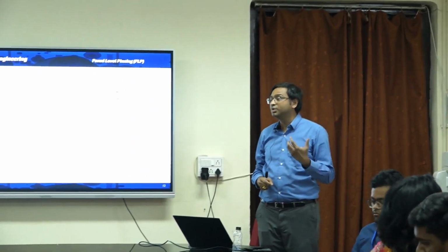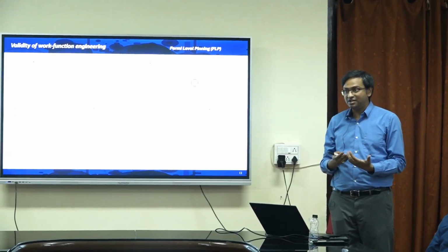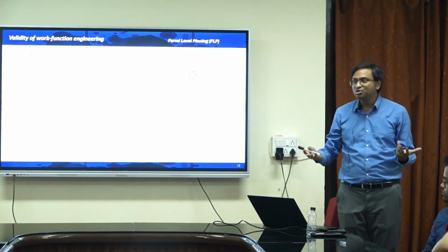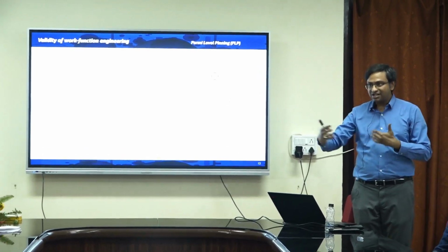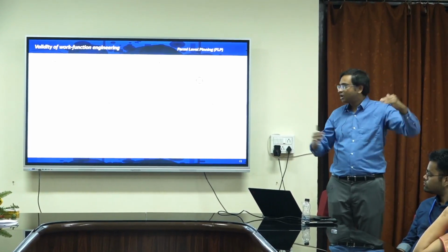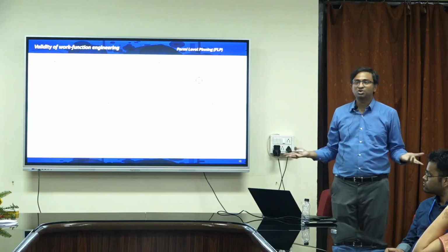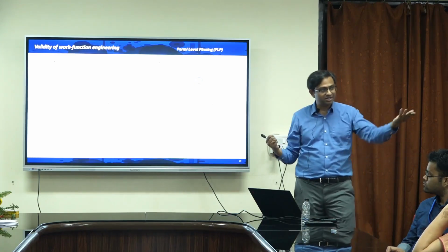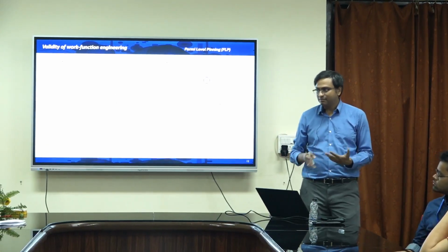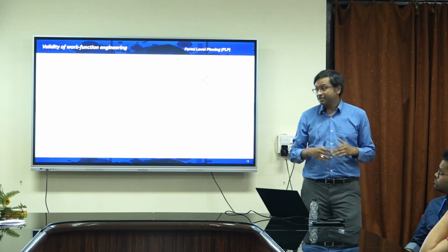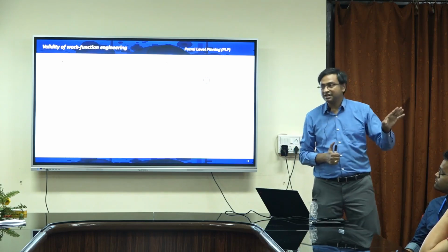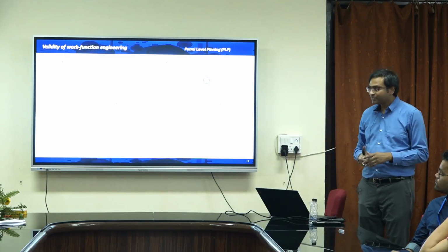It also has to come along with the electron affinity of the material and the band gap of the material, and a smaller band gap material is always easier to make contact with. A larger band gap material is very difficult because you do not have that big a span of metal work function. Metals are just only these, right? You can take the periodic table and find how many metals there are. There are some compound metals. You can engineer metallic compounds, right? But not everything is going to be easily integrable with the technology, right? So you see, there are challenges with contacts.